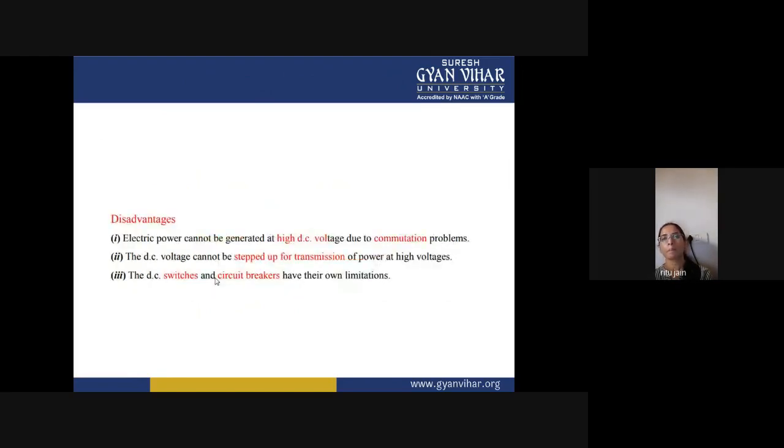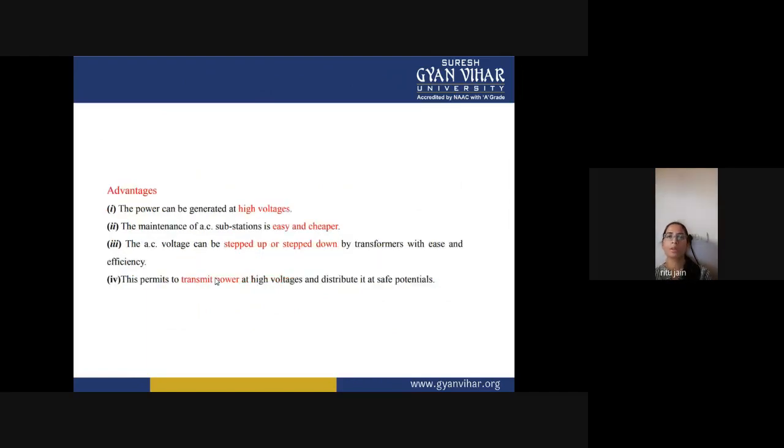The disadvantage is that electric power cannot be generated at high DC voltage due to commutation problems, the DC voltage cannot be stepped up for transmission of power at high voltages, and DC switches and circuit breakers have their own limitations. What are the advantages of AC?